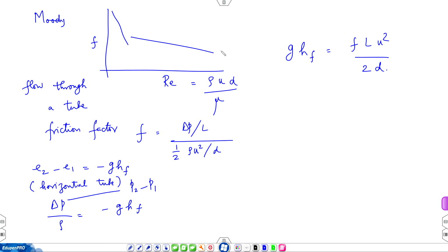That we have to examine, but there is a break in the curve. And this graph is for a smooth tube. Okay, a tube, let us say a polished tube, where there are no apparent roughnesses. If you think of, let us say, a concrete pipe, it is very rough. So, a concrete pipe has roughness, a steel tube will be practically smooth.